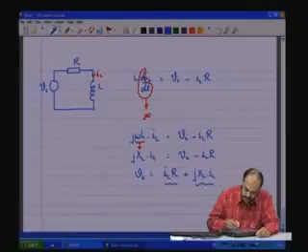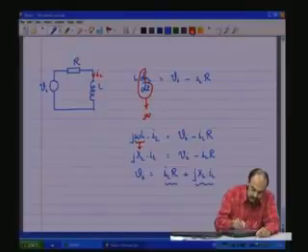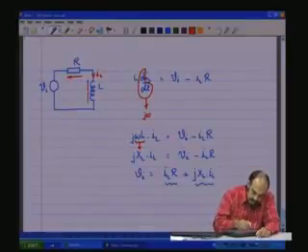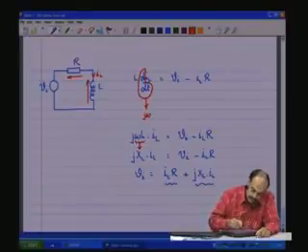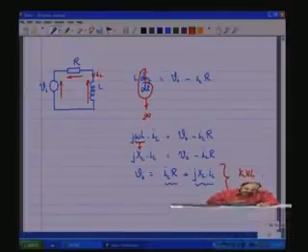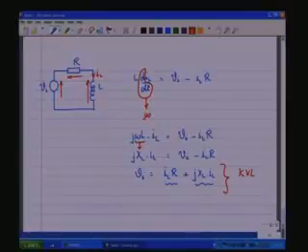You see, this is the voltage. IL into R is the voltage drop across the resistance. jXL into IL is the voltage drop across the inductance, which is VL, and we have Vi, which is here. So, observe that KVL is obeyed here, that is the summation of the instantaneous voltages Vi, IL into R and jXL into IL, they all sum up to 0 every instant of the time.